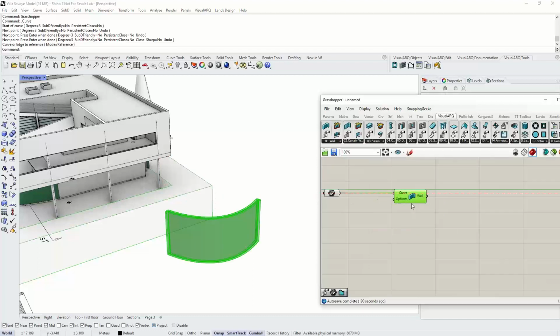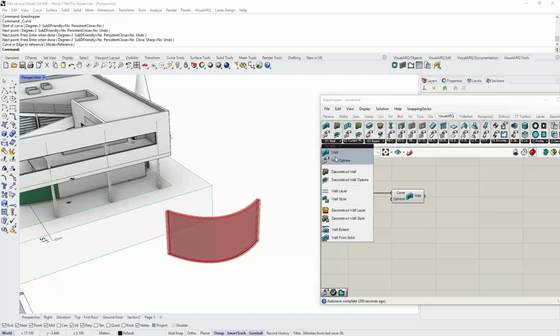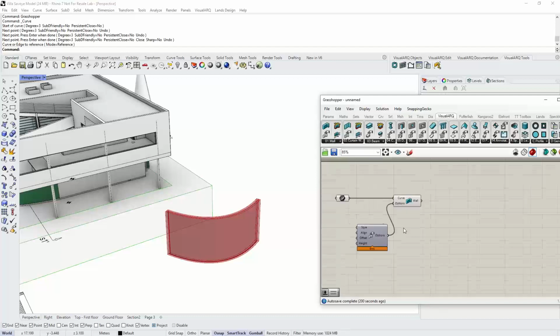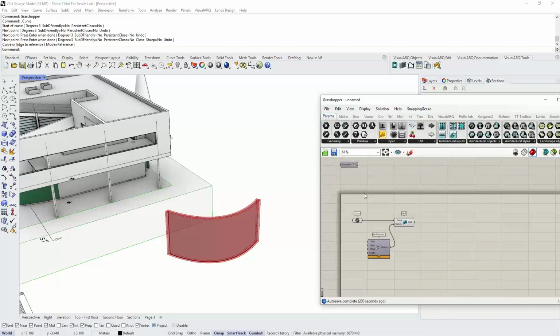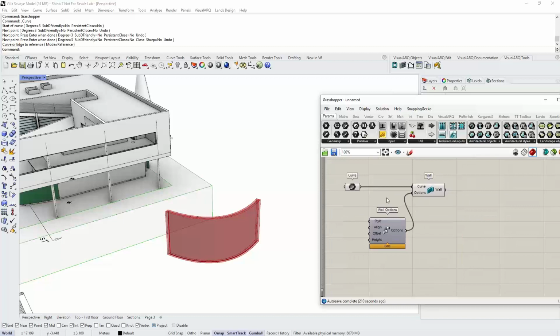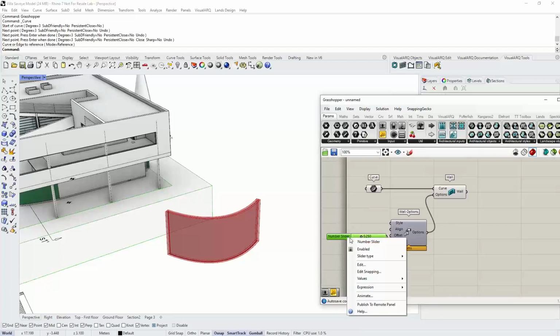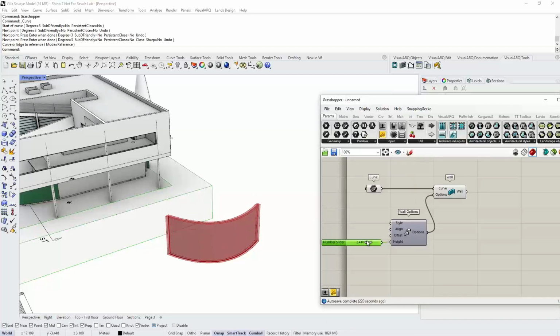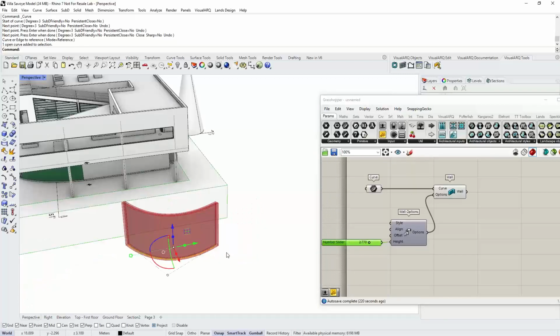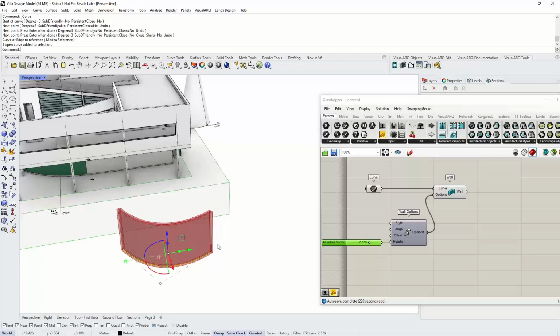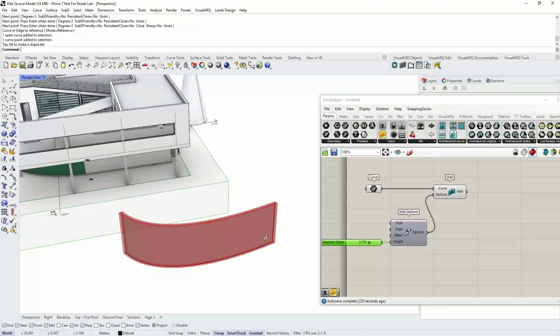And well, if we want to define more details on the wall, for example, which style is using, the height of it, the alignment, we need this wall options component. Okay, I'm going to use the focals to see the names of these components. And okay, with the number slider here, I'm going to set this maximum to 4 meters. We can change the height of it. All right. And of course, everything is linked with the original curve. Okay, so if I stretch this, it completes.